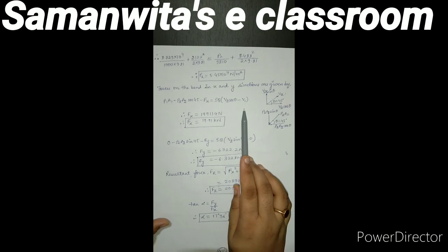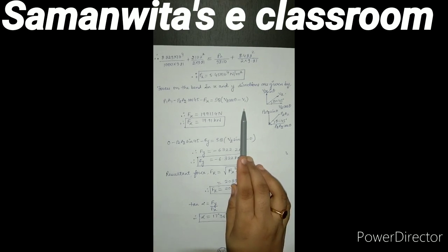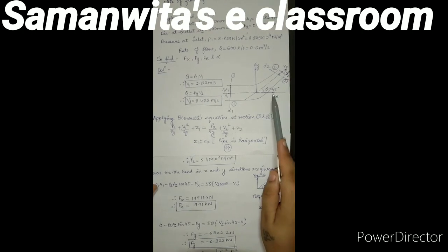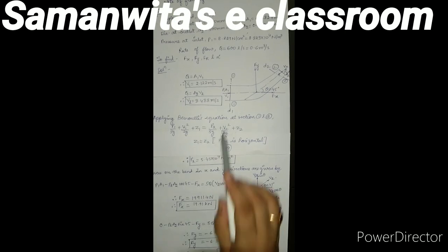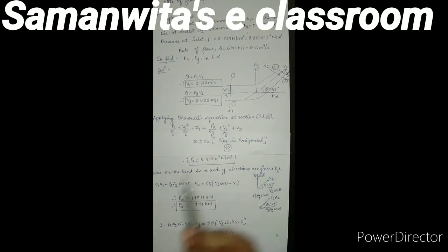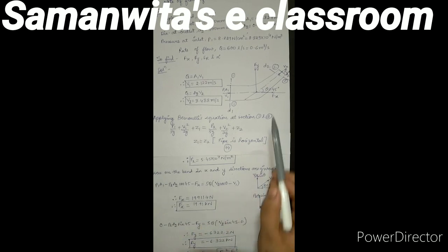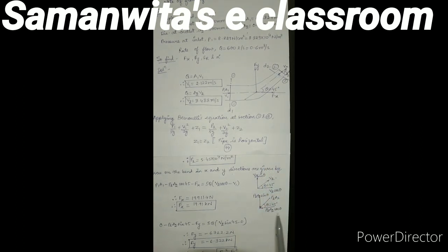So, I am going to again use the same equations as I used during the study of theory. Now, when I look at this figure, the equation has to be written with P1A1 in the positive x direction, so I take P1A1 as positive. Then I have P2A2, which I have resolved over here. P2A2 was in the downward direction. I have resolved it into a cos and a sine component, and V2 was in the outward direction, so here I have V2 cos θ and V2 sin θ. θ is 45 degrees. So this will be minus P2A2 cos 45,